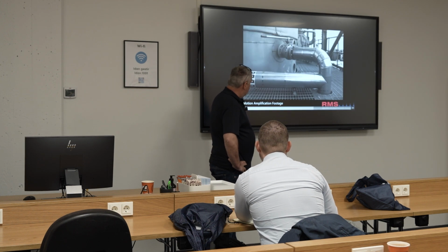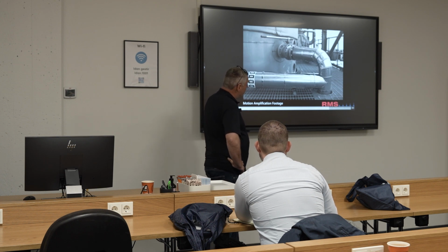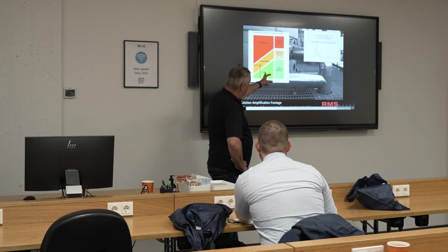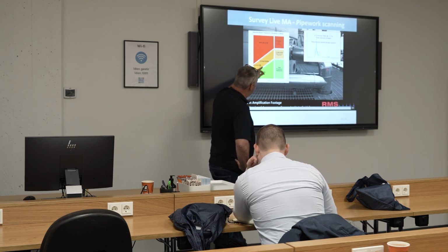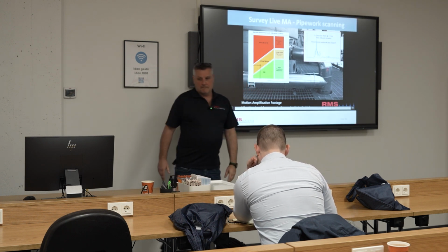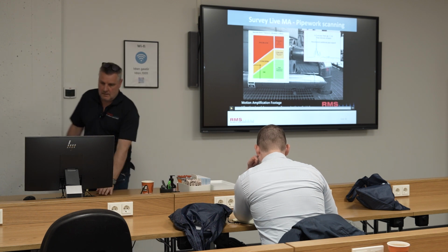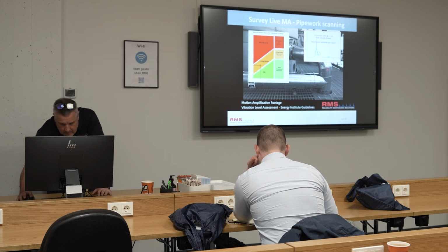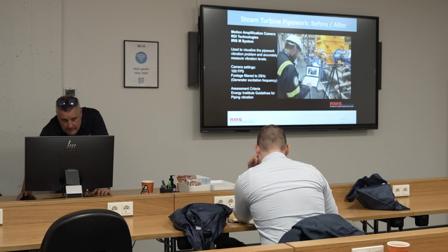But what we tend to do with it is look at this information and then put our tolerance on, like I say, the Energy Institute, and reflect vibration signatures from that. And that's the type of thing we're looking at, where you get, okay, concern and problem. So we know with a vibration up there at that frequency, we're in the concern. So it's nice to show the customer things like that.